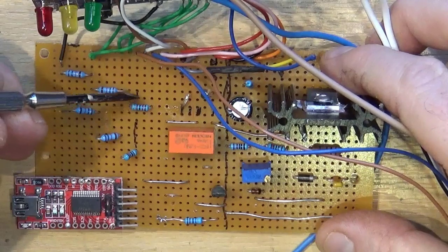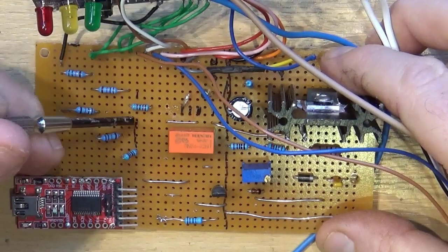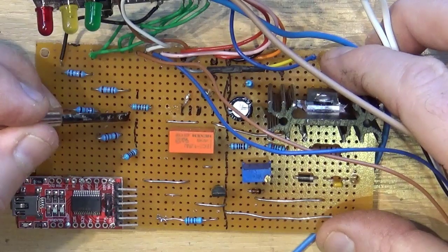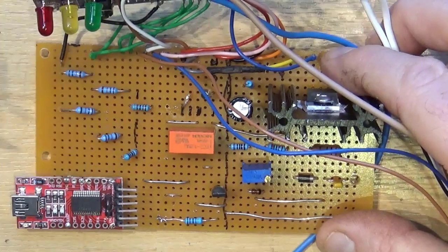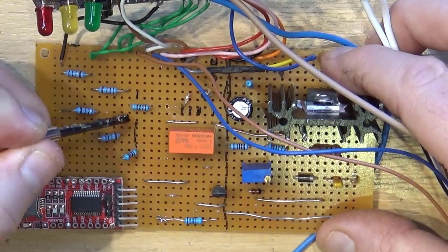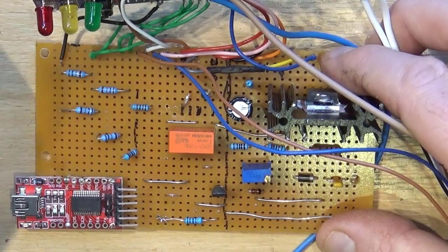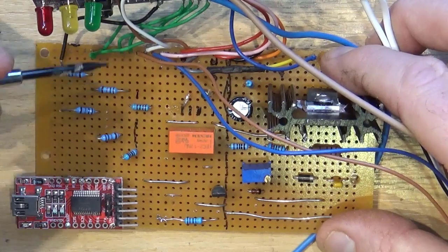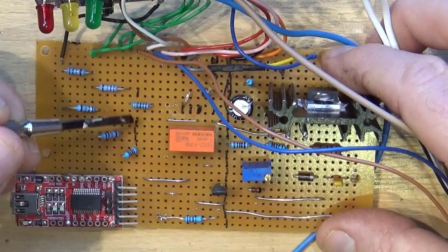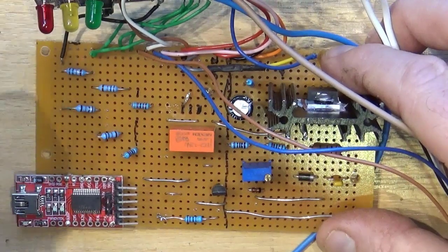Most of our resistors are these, and this is 0.1 of an inch or 2.54 millimeters per hole, so that's 3. These all want 7.62 between the pads, and I don't want to start mounting them on end like this if I can possibly help it.